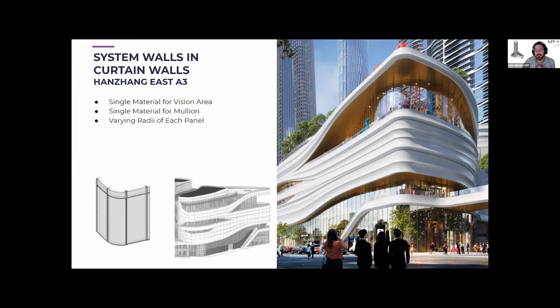The system I came up with was to build a loadable family, which has an arc in it. You can set the radii, it flexes itself, it has mullions in there, and I thought it was a pretty good solution. The solution the team came up with, which I think is better, which is why I'm presenting that instead of mine, is they used walls. Within curtain wall systems, you can actually use a wall itself as the panel. The advantage is that a wall within Revit, when loaded into a curtain wall panel, will take the radii of the host itself instead of faceting like a loadable family.